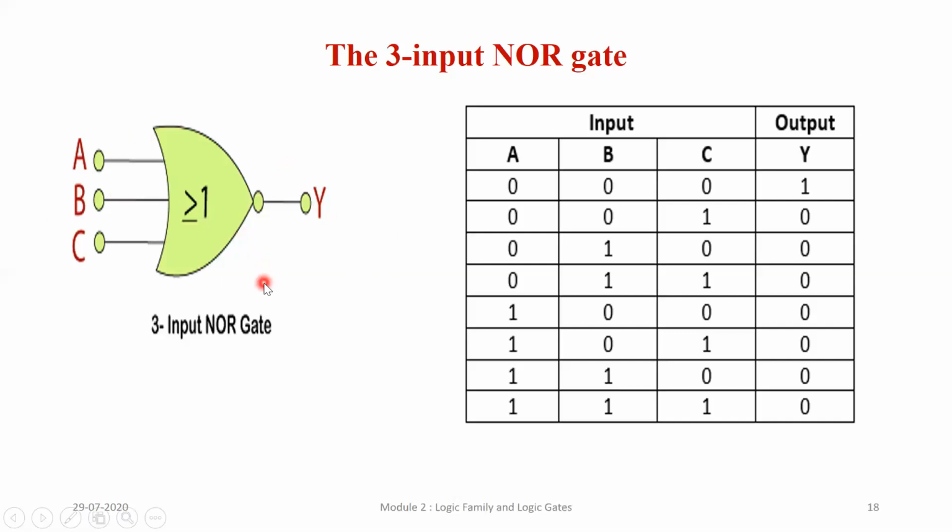So you need to know which pin is VCC and which pin is ground, because all these ICs work with some amount of supply, since the transistor inside should be switched on. For the TTL family, we have to give 5 volt. From the battery, we give 5 volt. We should not exceed 5 volt, and 5 volt and ground we connect to those pins.